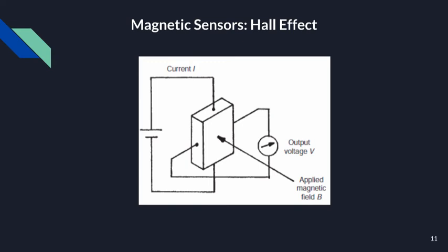The conductor in Hall effect sensors is usually made from a semiconductor material as opposed to a metal, because a larger voltage output is produced for a magnetic field of a given size. In one common use of the device as a proximity sensor, the magnetic field is provided by a permanent magnet that is built into the device. The magnitude of this field changes when the device becomes close to any ferrous metal object or boundary.